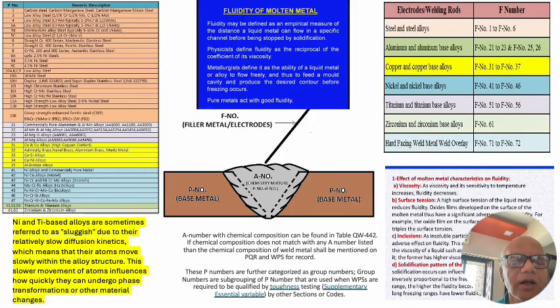And the electrode is going to be 0.1, so 80% of that is going to be 0.08. And 0.08 and 0.04 add up to 0.12, so it is a little more than the filler wire, and that's how the A number differs from the filler wire or from the parent metal. And therefore the three numbers are very important for us: the P number, F number, and A number.